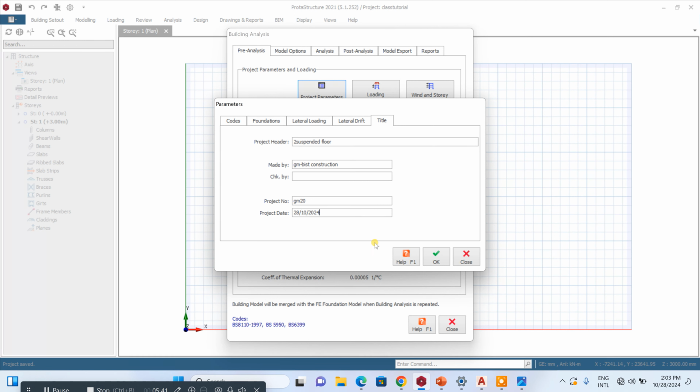Okay, let's check the length of our beam. Once you click, you can see the length there. Beam length 6096. You can actually see that this is long, so we can change the size of this column to 450. Okay, let's look at it. Let's check this one. 6.1. And so there's a wall here, so we'll now edit this one. 450.